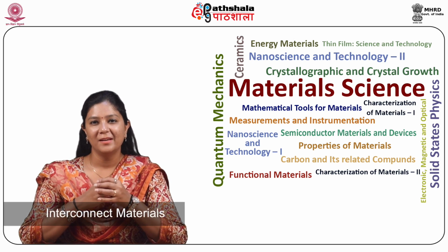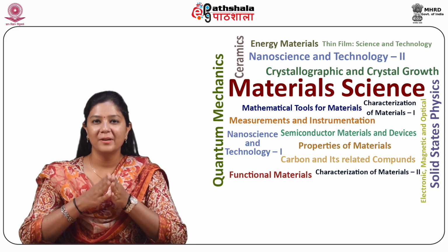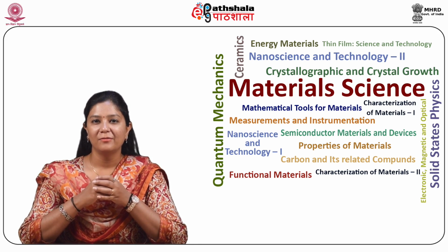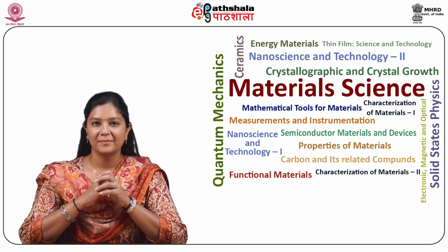Broadly, interconnect materials for SOFC fall into two categories: conductive ceramics, that is perovskite materials, for operation at higher temperatures, and metallic alloys for lower temperature operation. The ceramic interconnects used in higher temperature SOFCs are primarily doped lanthanum and yttrium chromites.